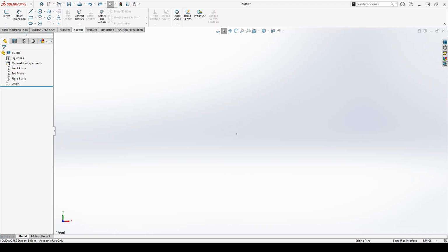So this problem looks like it is symmetric. Sketches are fully defined, the origin is indicated in red. But from the first look of this problem, I don't think the base can be fully constrained by creating the base pad first, because I haven't constructed the side pad to constrain the bottom length to the bottom side of that. So let's make the side pad first.